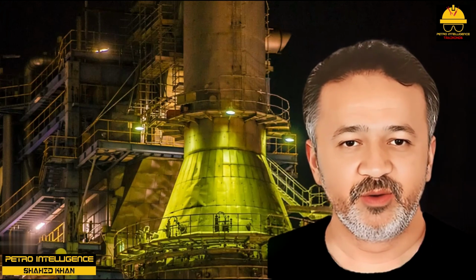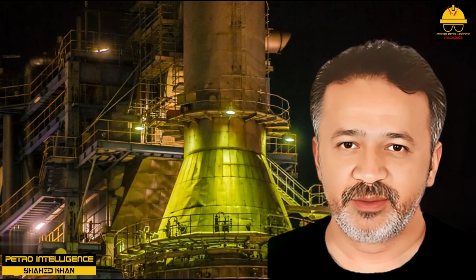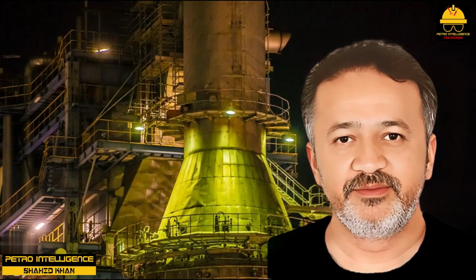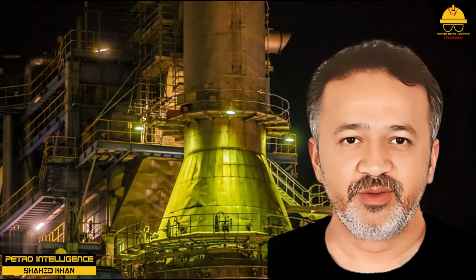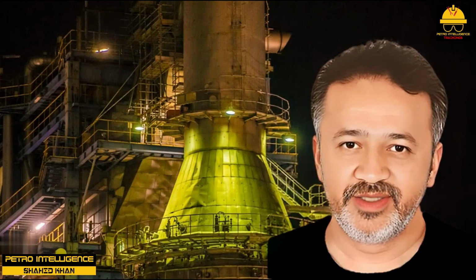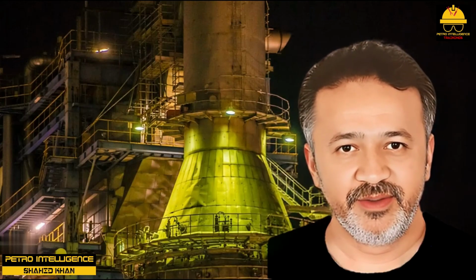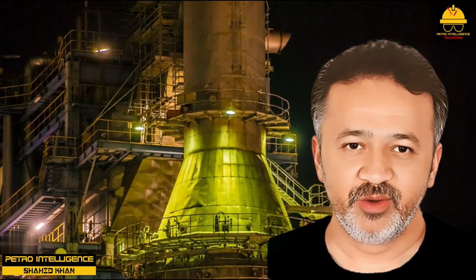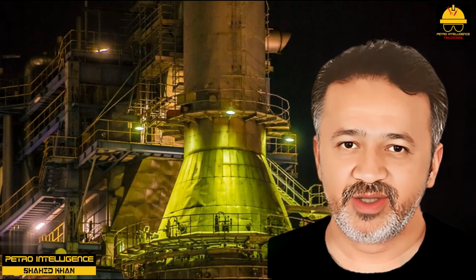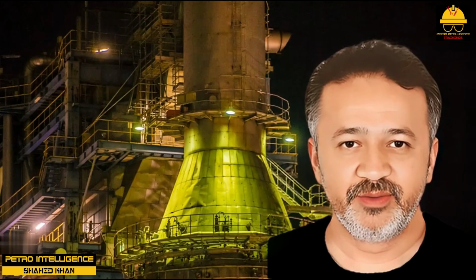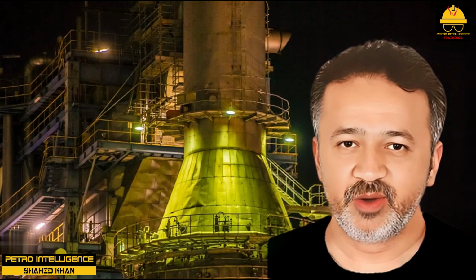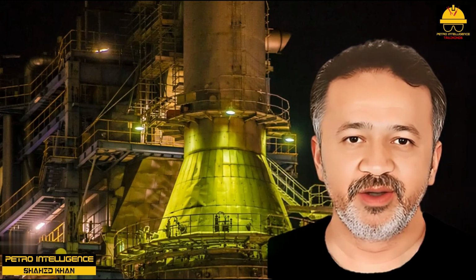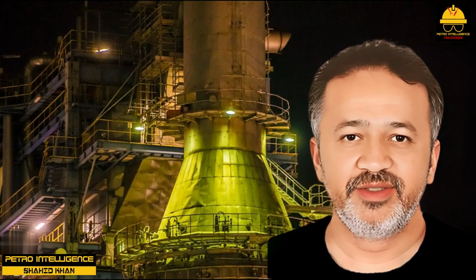So, what can we do to actually run more crude, especially as there is no bypass around this new air preheater? The answer, of course, is to allow more air into the firebox and thus generate more flue gas. The firebox oxygen was increased from 3 to 6%, which reduced the firebox temperature to its pre-revamp state. This, in turn, increased the pounds of flue gas flowing through the convective section and increased the heat absorbed in the convective section. The increased combustion airflow was needed not for combustion, but to transfer heat from the radiant section, the firebox, to the convective section.